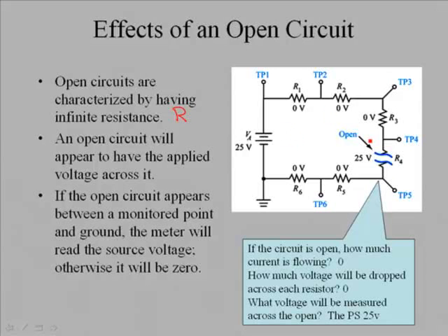In the circuit here we have a component, and we're showing a resistor here, and the resistor is open. Now, commonly what will cause this is too much current has flowed through this circuit, and this particular component may have just disintegrated, burned up, and you look into your circuit and you simply see a charred component there. And if you were to measure from test point 4 to test point 5 with an ohmmeter, you would commonly expect to see infinite resistance, because this component ceases to exist because it's simply burned up.